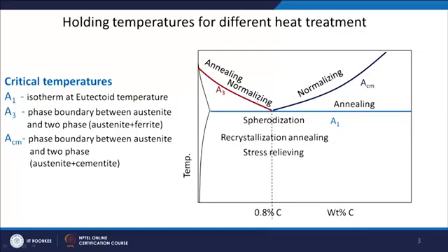Right now we are concentrating on the bulk heat treatment. Before going further, let us see what the important temperatures are in the iron-carbon phase diagram. We are mostly concentrating on the part where the steel is going to be, and also only on the part where you are going to have a solid state phase transformation. So you have austenite here, and you have alpha ferrite here, and on the other side you will have cementite, and this is where you will have the eutectoid reaction.